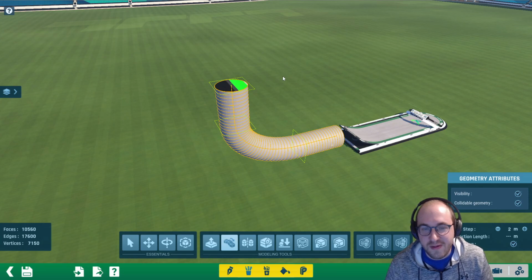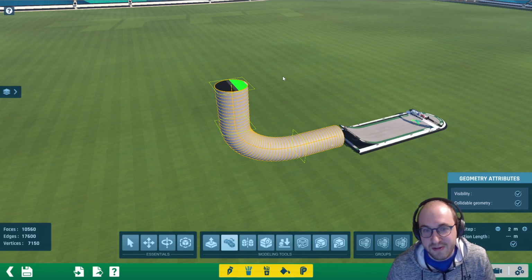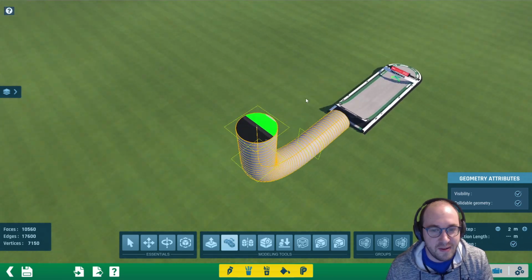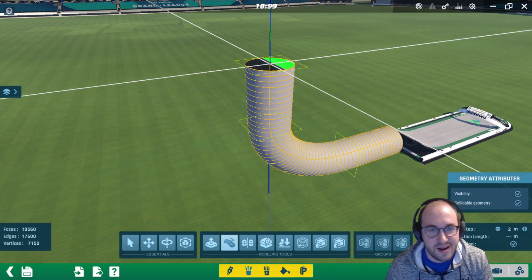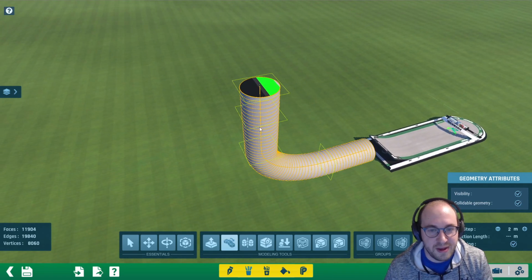And so we'll create a new section up here. You could create different blocks for different sections of the pipe. Probably would make things more reusable, but depending on your track, you might be specifically trying to connect 2 points where this type of thing can be pretty helpful. So we'll click on the green dot, create another new section of pipe, and this one's going to be now a curve to the left.